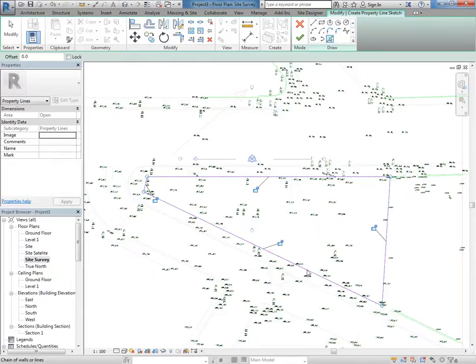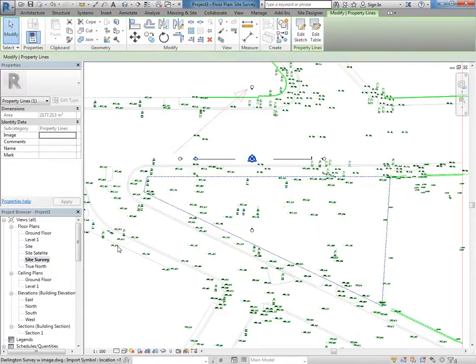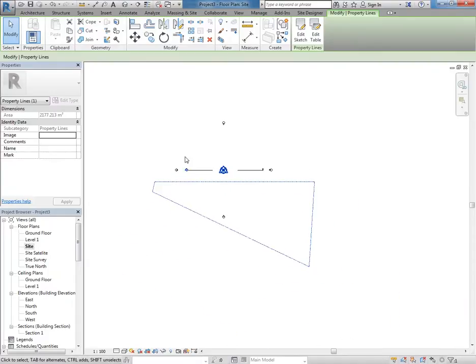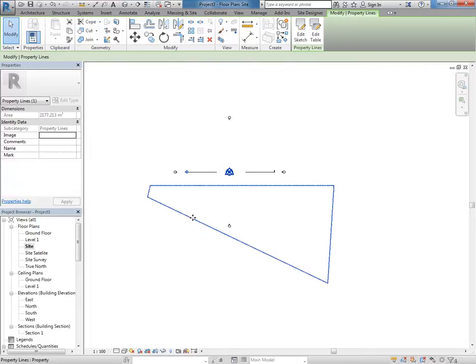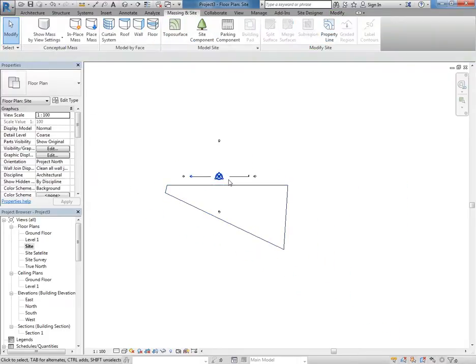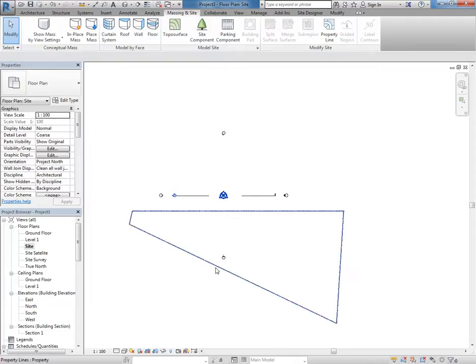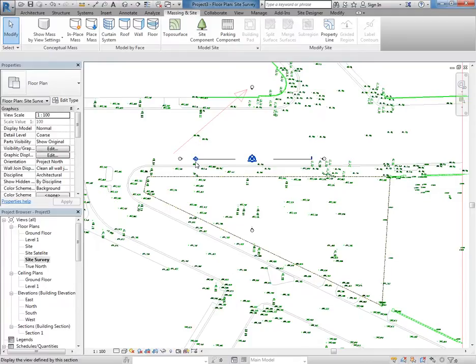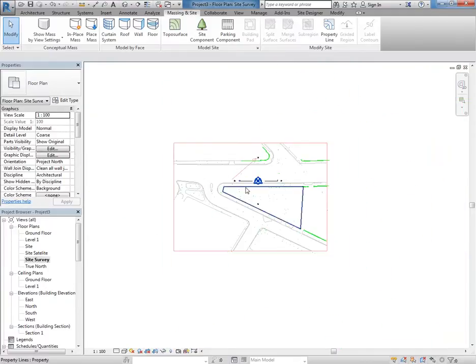Done. Tick to finish. And now to make sure that's working, I can go back to my original site plan, just to make it clear why I've duplicated all of these views. And I can see the site there fairly clearly. The problem is that it's actually a bit low. So I want to move that now to a better location. I'm bringing up pinned, so it's a little bit out of order, but it's good because this is the way you really will do things in real life.